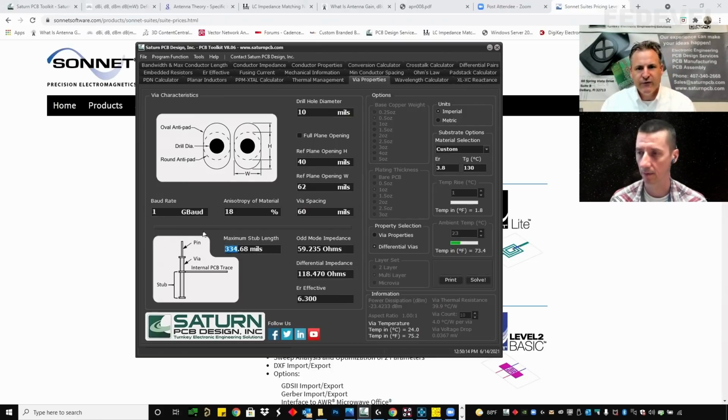Okay, I understand now. Before it starts really affecting things. If you're up at 10 gigabaud, that goes down to 33. So if you've got an 062 board or an 090 board backplane, because some of these backplanes are thick, I mean, they're 90 mils, 125 mils thick, that means if your stub length is longer than 33 mils, you're going to have to cut it out. You need to do back drilling. You have to back drill, yeah.